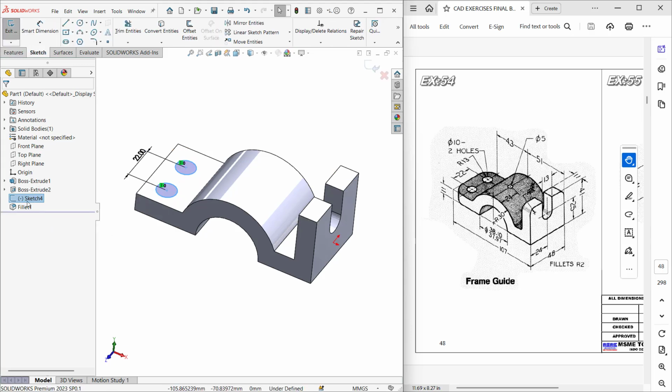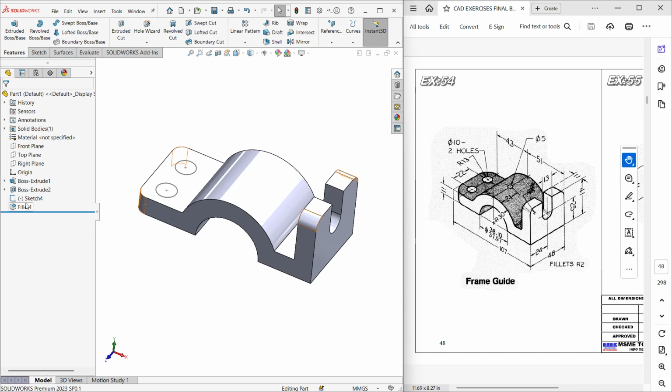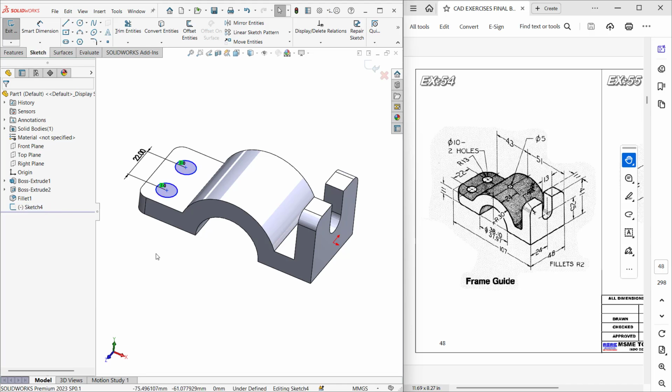Now what the software thinks is I'm doing the editing here, and whatever features are coming just below, it is not at all made. Likewise, the software algorithm thinks. Now what do we do with this? The best option is to exit the workbench and move the sketch downwards. Then the software thinks the fillet has already been created. Now if I edit or create a sketch, it will take this fillet into account also. Okay, yeah, so I did this one.